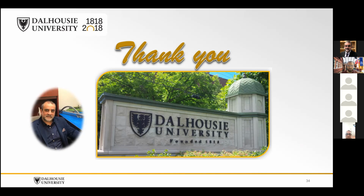When you are in doubt or when you are missing some data, you're going to go with some correlations for similar soil. So you need to dig a lot in the literature. What I'm always saying is that if the job is assigned, let's say, 100 hours to do the design, you need 30 hours of reading literature: what others did in the same soil, the same conditions, what problems they faced.